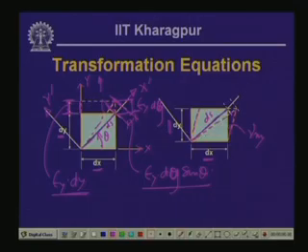Again this angle is theta as we have defined, hence this is theta. So, the extension because of shearing strain is equal to gamma xy times dy, and the extension in the diagonal is given by gamma xy dy cosine theta.